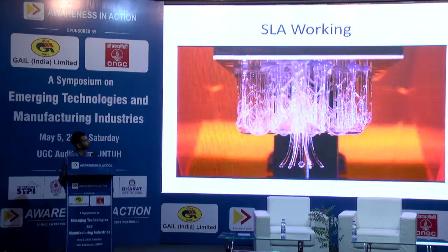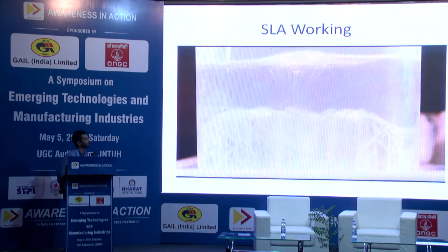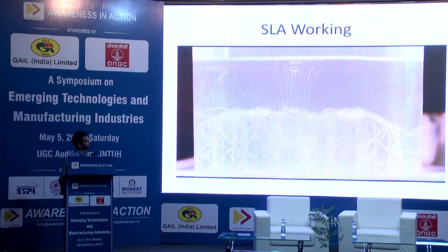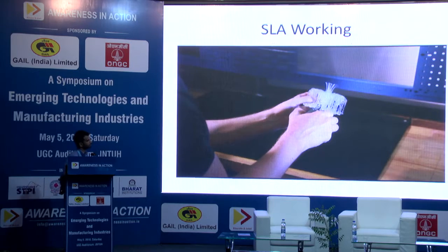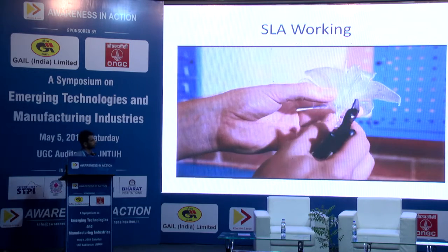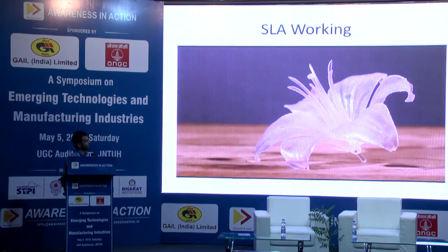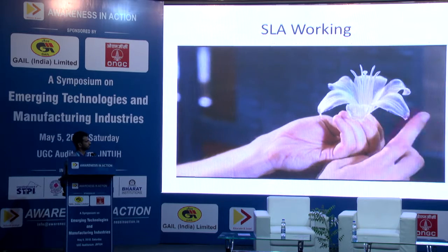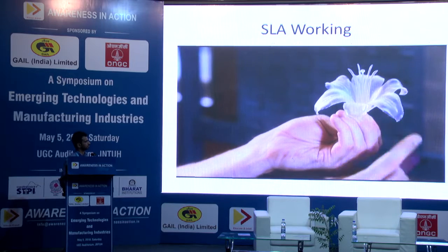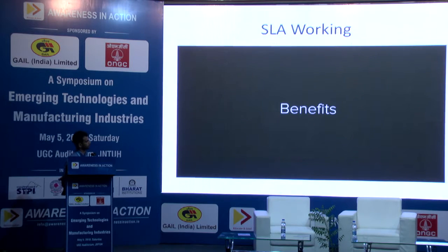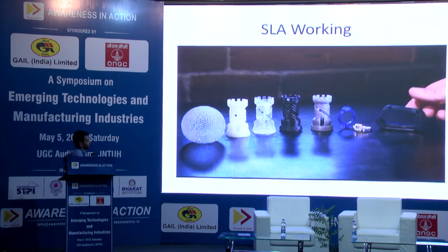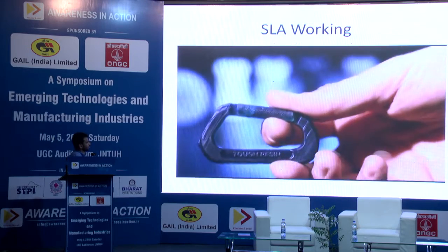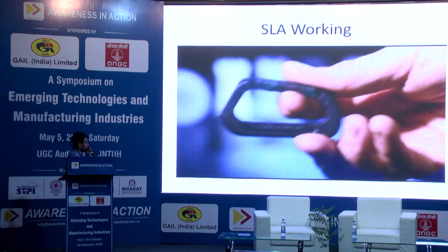We'll take our printout and wash it in rubbing alcohol to get the excess resin off. The flower comes with supports on it, and we'll snip them off to finish the piece. Stereolithography is known for producing extreme detail with layers down to 4 times finer than a human hair. The Form 1 Plus lets us take advantage of a library of materials, so we made some other parts to show what these resins can do.